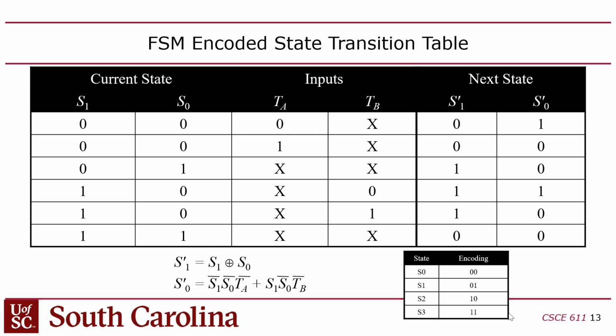So this logic would be different if we applied a different encoding to the states. This is the reason why in SystemVerilog they wanted to give the programmer the ability to use enumerated types for the state, because then, presumably, I don't know if it actually does this, right? But ostensibly, the synthesizer is going to pick encodings that will give you the minimal logic for the next state logic and the output logic.